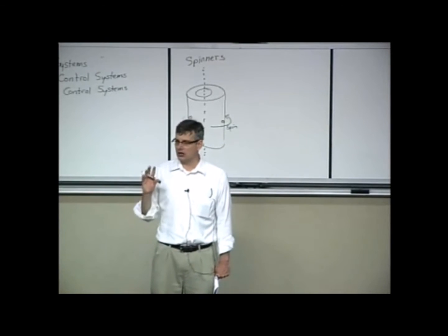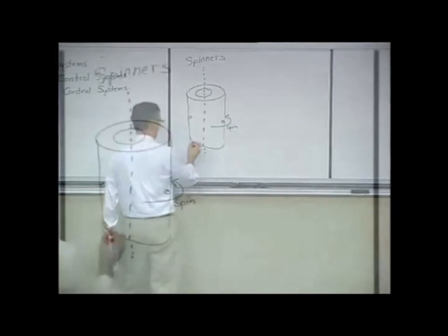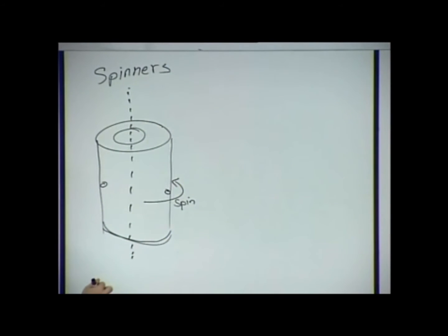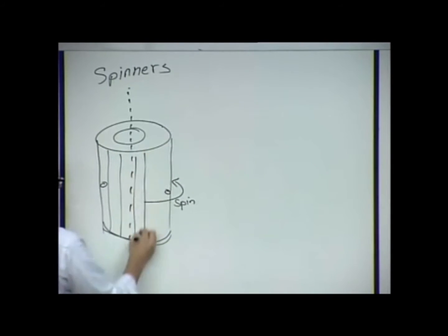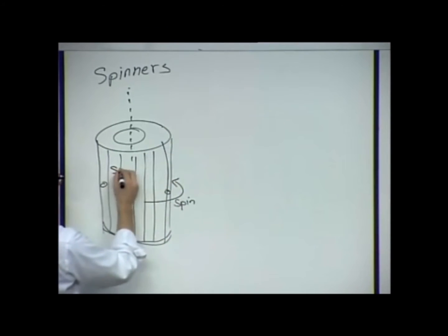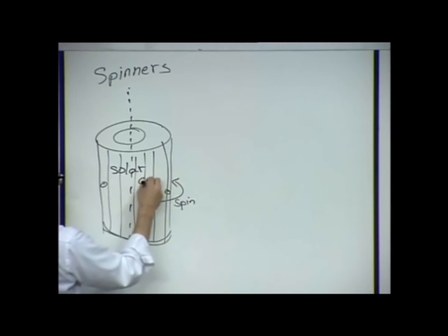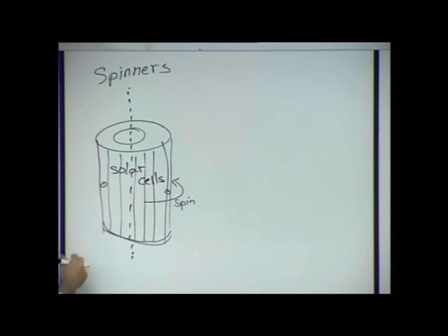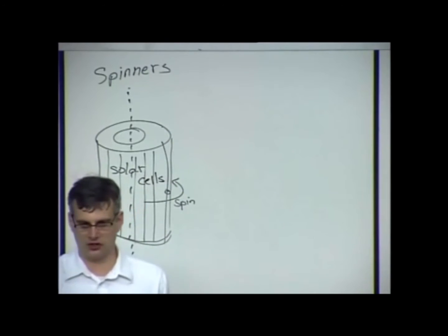First of all, you need power. And so the power source of choice in space, especially for Earth-based satellites, is almost always solar cells for their longevity, amount of power that they put out. We'll get into power spacecraft subsystems in a few minutes. But you usually plaster this thing with solar cells so that as this thing spins around, one side of it is always facing towards the sun.